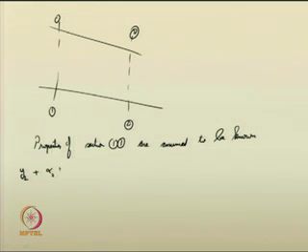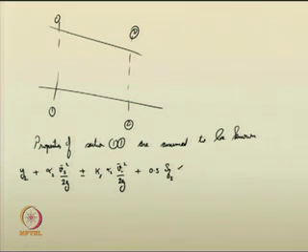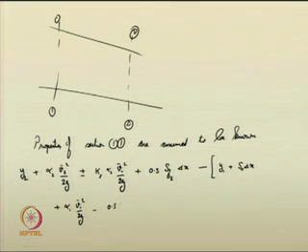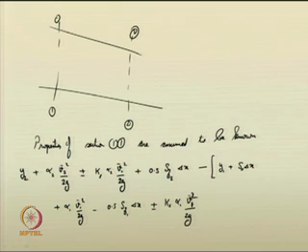So, alpha 2 V2 squared by 2g, it can be plus or minus, we are not sure, based on the magnitude of the velocity, plus 0.5 SF2 into del x, minus, I am just writing it like this, y1 plus S0 into del x plus alpha 1 V1 squared by 2g minus 0.5 SF1 into del x plus or minus KL alpha 1 V1 squared by 2g.